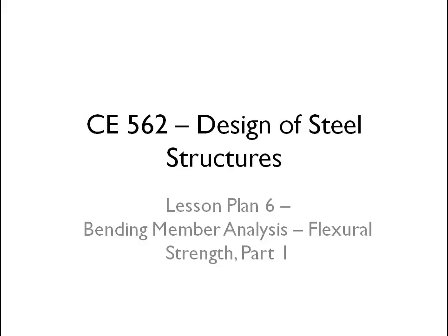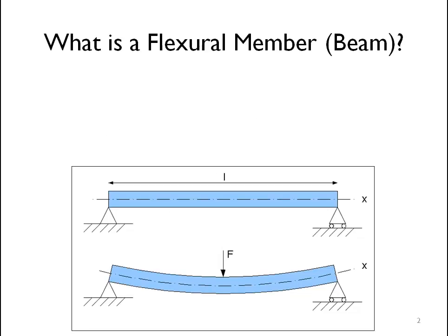first. One of the first things I want to get out of the way is to make sure we're all on the same page with what I mean when I say a flexural member or a beam. And I've included a sketch here of a very simple schematic of a flexural member. One thing that we note about this beam is it's being loaded perpendicular to its longitudinal axis. So here's the longitudinal axis. The load is being applied perpendicular to that. And the effect of that is that the primary stresses that are being induced in this section are bending stresses. And that's really the fundamental basis for our definition of a beam.